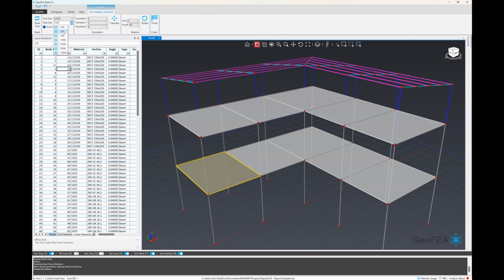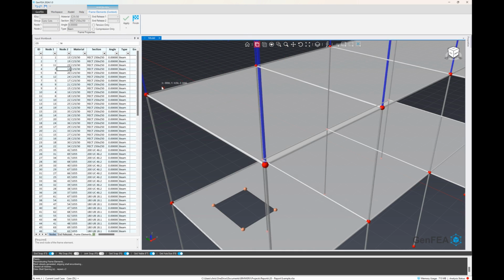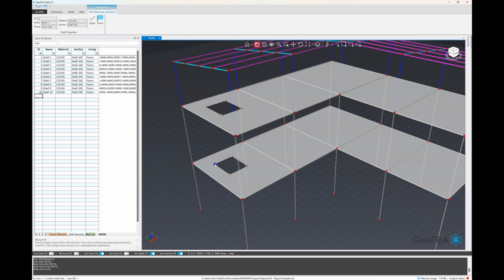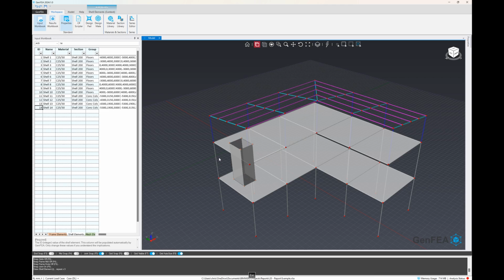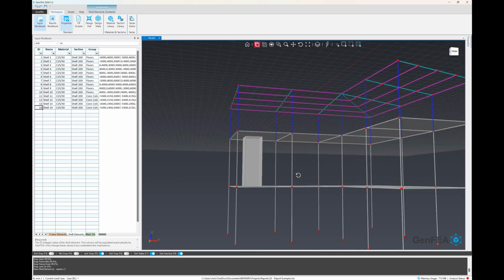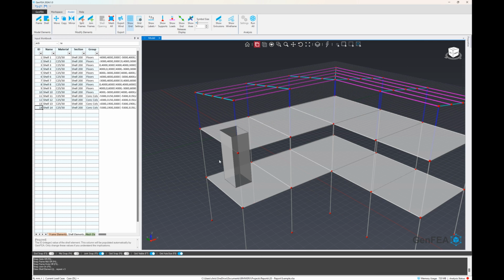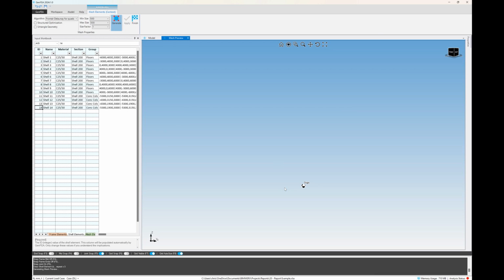So we'll adjust our grid settings and then create two openings in the lower and the upper shell element. And then we'll use the draw shell tools and toggle our grid snaps and joint snaps so that we can easily create those vertical shell components, as you can see. Right, so now that we have completed drawing in our example shaft walls here, we can head over to the mesh tool and we can click generate using just the